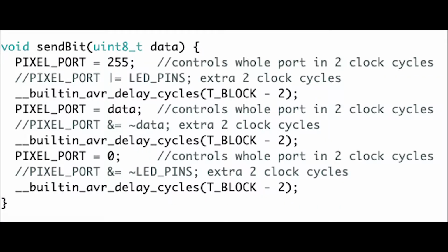While waiting for them to arrive, I continued with software. Here I figured out that all the pins on a port can be toggled in one command, allowing for parallel writing of bits instead of serial writing, therefore increasing the frame rate of the matrix. As you can see, a low-level write to a port only takes 2 clock cycles, therefore the 8 pins can be controlled in parallel on this one line.